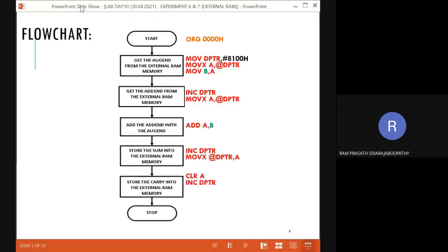You can use this anywhere. After you have stored the sum into the memory location pointed to by DPTR, you can immediately use INC DPTR. Fine. Now, coming to this particular concept, here I am going to test the carry flag. If there is no carry, I jump to skip, to wherever I have placed the label. Suppose there is a carry, what should we do? The accumulator now has 00. If there is a carry, what should we do? Any idea?